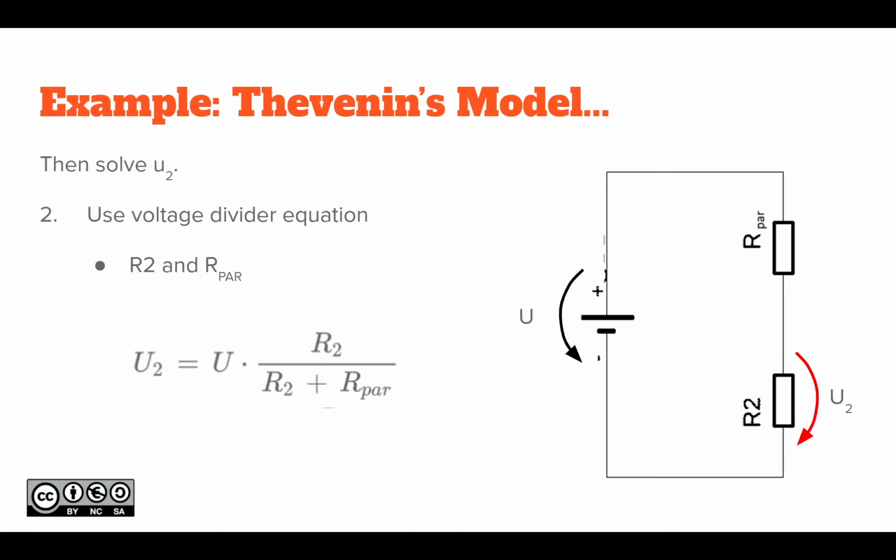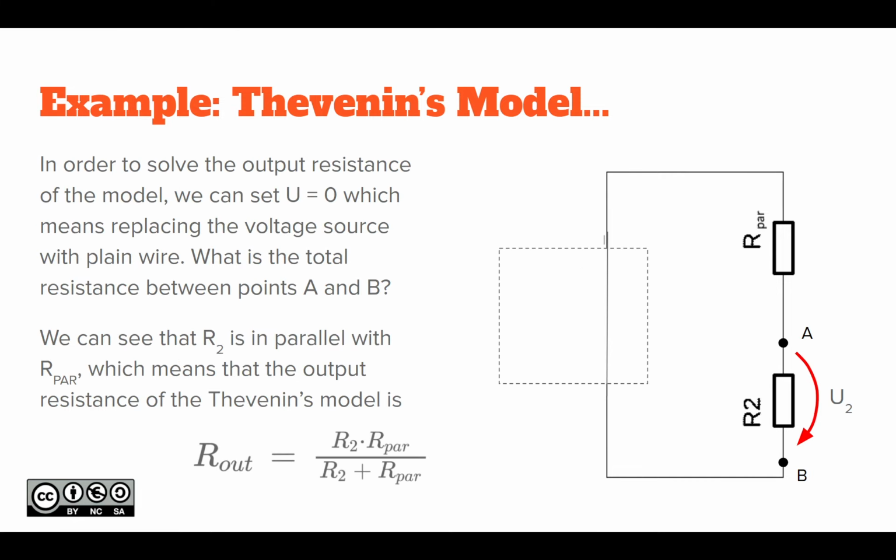It means that it can provide lots of current to any load. So if we can control the U, we can also turn it off, meaning turning the energy off, which means that for the analysis, we replace it by a plain wire. Remember, this is theoretical stuff. Never replace a voltage source by shorting it. Sparks will fly, and that's not usually good.